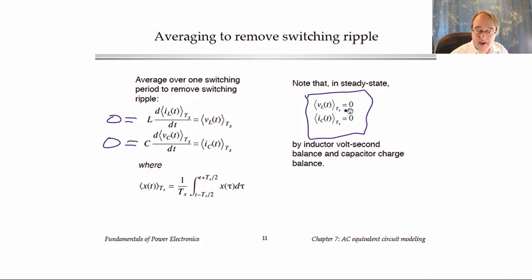And the right-hand side contains an average inductor voltage or an average capacitor current, and these are in fact the volt-second balance and charge balance equations that we already know how to find. And so the bottom line is, all you have to do is take the equations that you already know from volt-second balance and charge balance, and instead of equating these voltages and currents to zero, we equate them to L di/dt or C dV/dt. So in fact, averaging is a small step from what you already know.